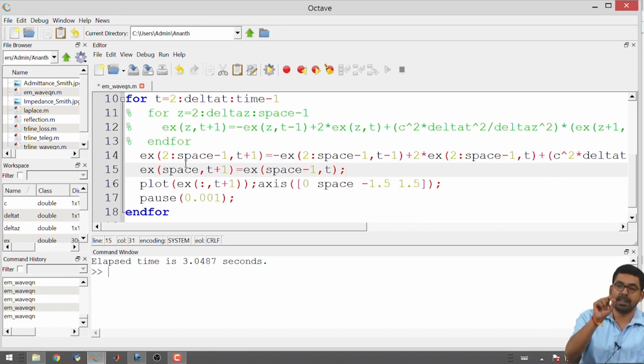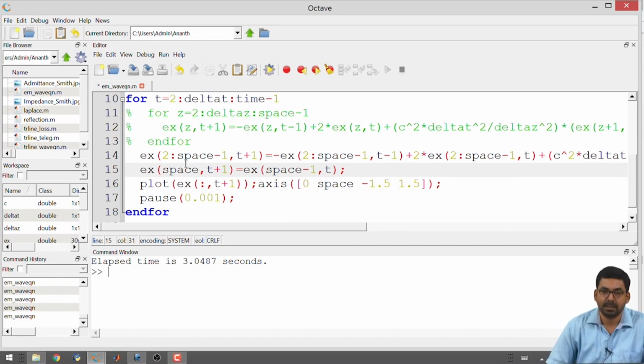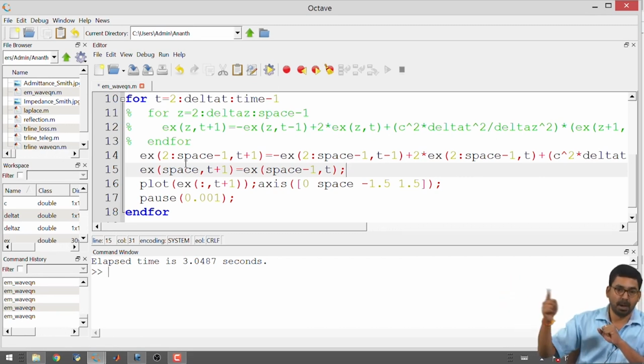You know that at the next instant of time the peak is going to appear at the next spatial location. If that happens, the wave is traveling in one direction. Implicitly your wave equation is doing that, but when it encounters a non-uniformity, it also calculates accurately and tells you that there is some impedance mismatch, so it is bouncing back.